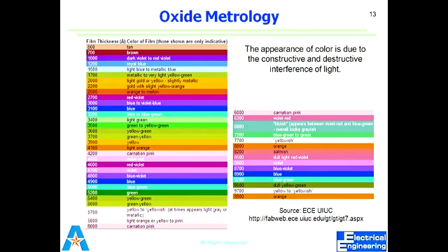You will see that after the end of the oxidation experiment in the lab, your wafers, which initially were gray because it was silicon only, are at the end blue. Due to the oxide, they are royal blue or light blue, just like sky blue. That is because it means they have a thickness of 1200 to 1500 angstroms of oxide.